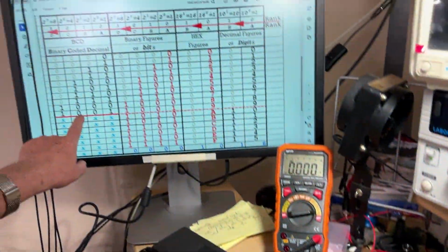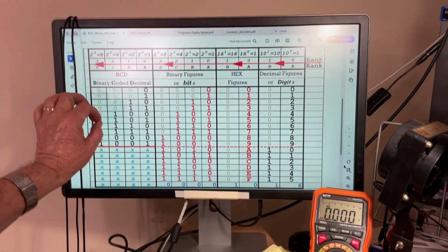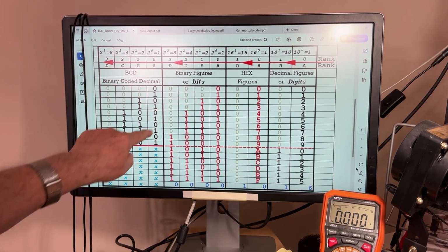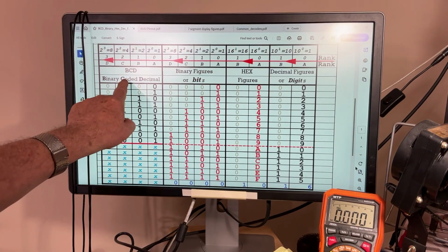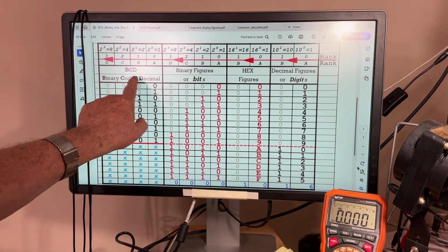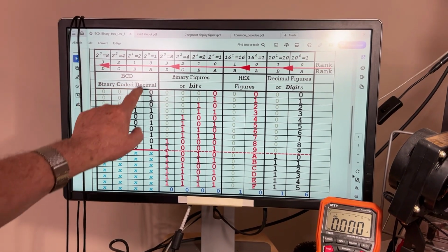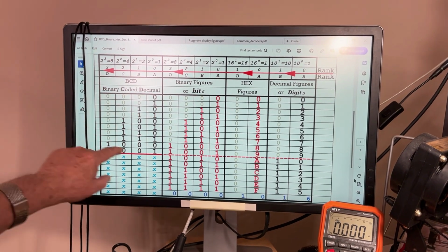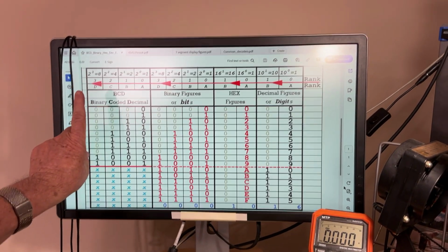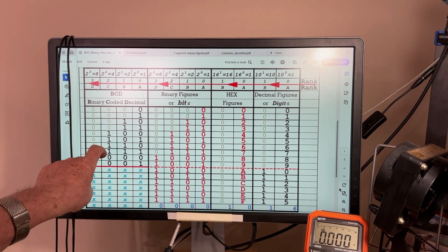So this is the famous BCD code. What does BCD stand for? It's a decimal number, but it's coded in binary. So binary coded decimal, and you get the acronym BCD. That's it. This is only designed for digits, because on 1 digit, you can only display numbers from 0 to 9.